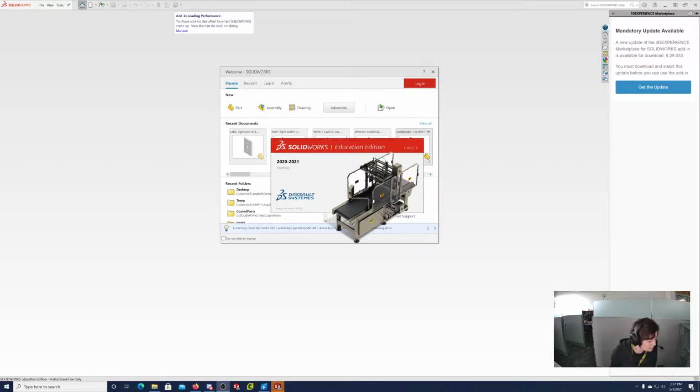So if everybody wants to go to page 7-24 in your textbook, we'll just start there. You'll see the tools needed on that first page. Basically, the SolidWorks tools that we'll be using are Sketch, obviously. We always use that pretty much. Geometric relations, a revolved cut, which is like a revolve, but you're cutting. So it's kind of like the difference between an extrude and an extruded cut. A revolved cut is kind of the opposite of a revolve, if that makes sense.